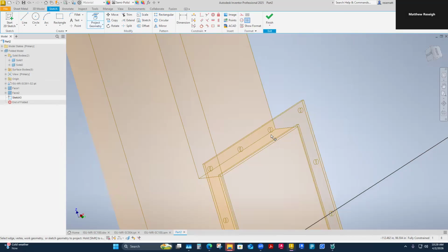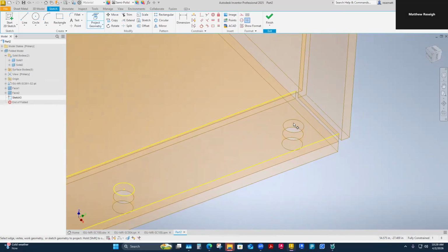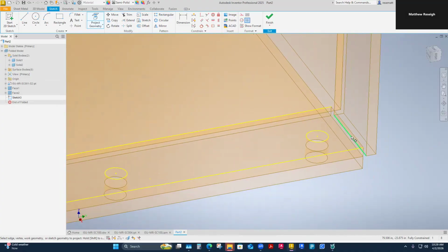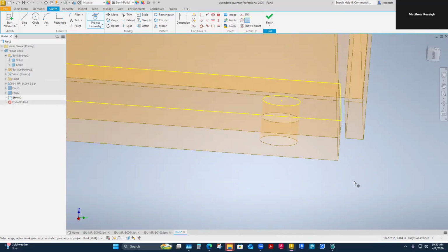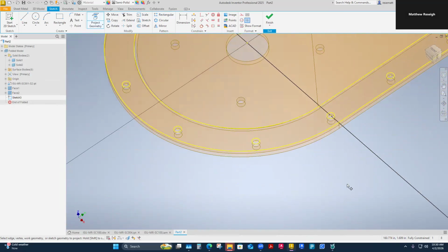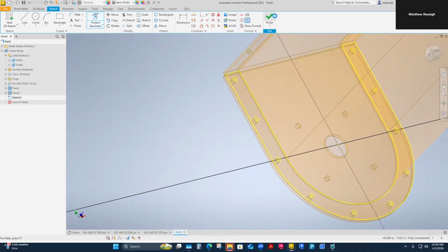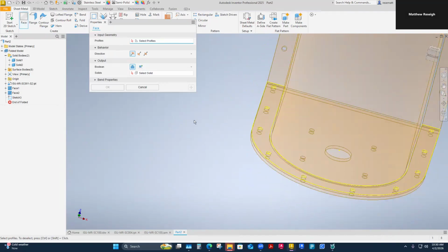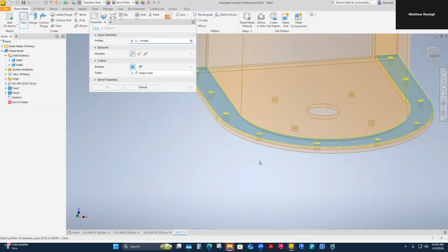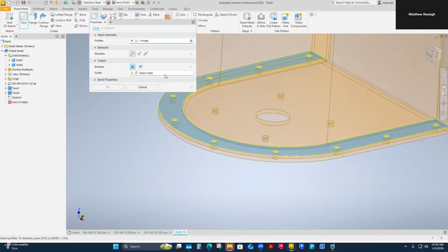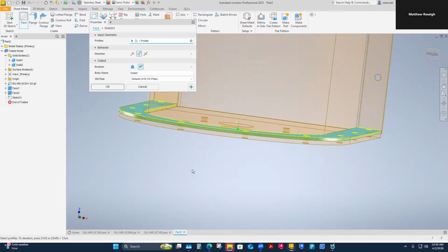Do you have this one up here to test on? This flange? That one? Okay, we'll do that one in just a second. I'm going to finish this one. That's my entire U-shaped with hole patterns in it projection. I'm going to say finish that. And I'm going to say face that. I had to select that profile to face it and then select the solid. I want to make a new solid. And then I want to make sure it goes the right direction, which is right there.